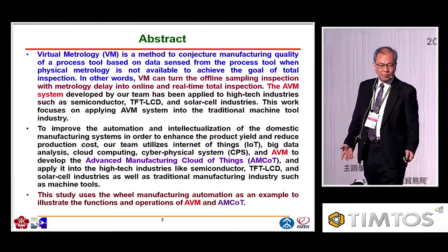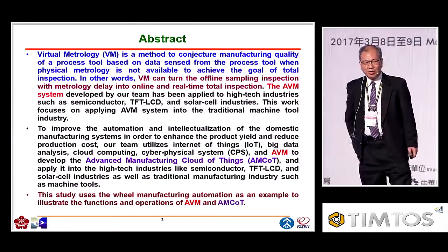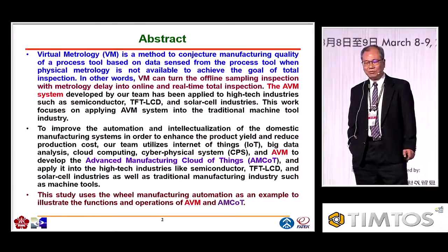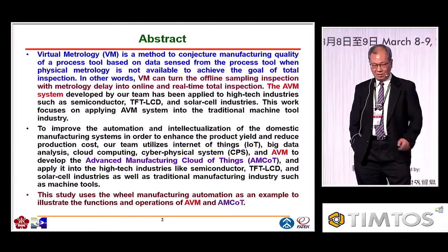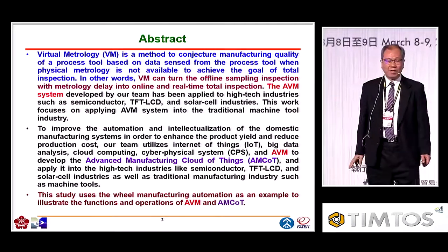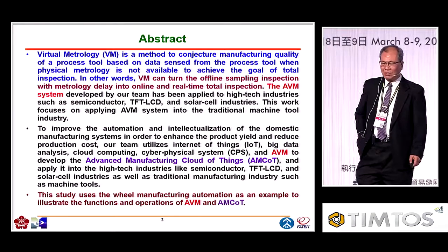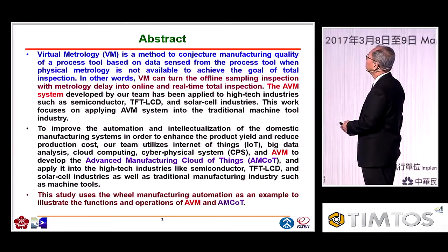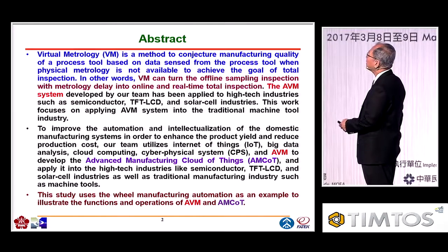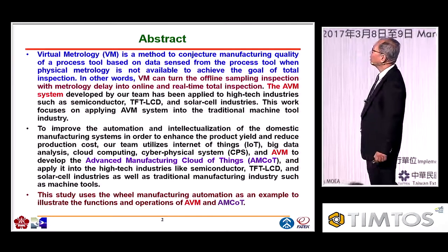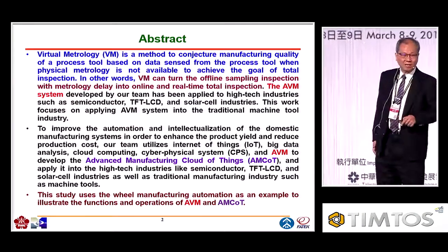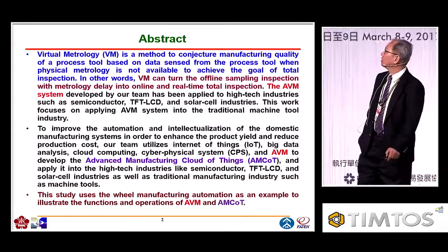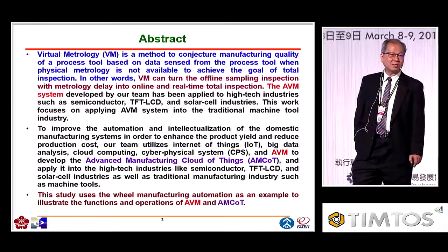Virtual metrology is a method to conjecture manufacturing quality of a process based on data sensed from the process tools without real physical metrologies. So actually, VM can turn the offline sampling inspection with metrology delay into online and real-time total inspection. This technology was actually requested about 10 years ago by the semiconductor industry.